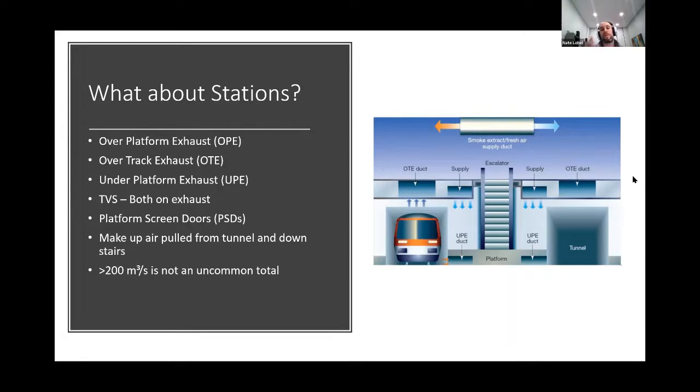Along a long running tunnel, we're looking at the longitudinal and it's not really that relevant. If you look at more of an interchange or a shallow bus station, wind effects are much more prevalent and much more involved and should be considered. And while you asked about tunnels, I will bring up that in buildings, where exhaust points are put really needs assessment, in terms of wind overcoming smoke exhaust systems themselves, preventing them from operating, not just adversely affecting makeup air.